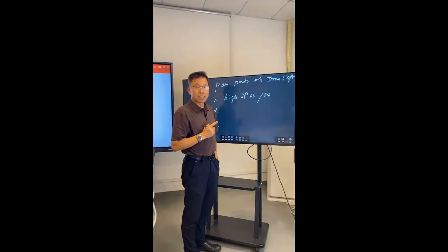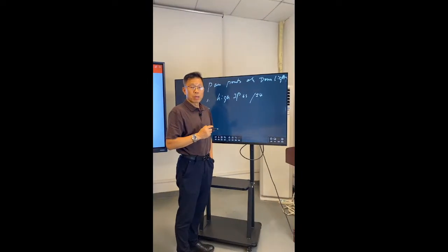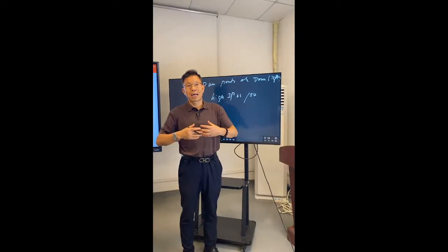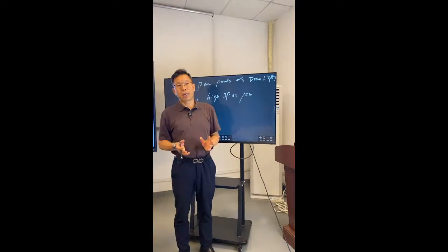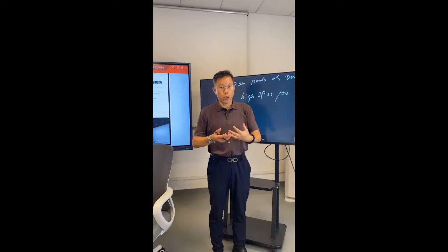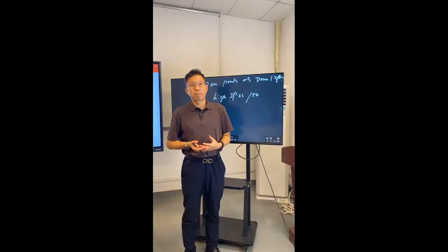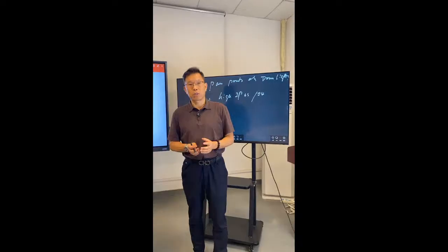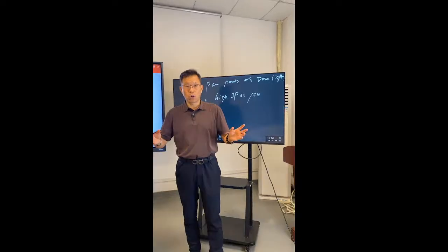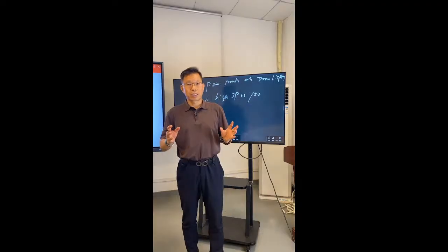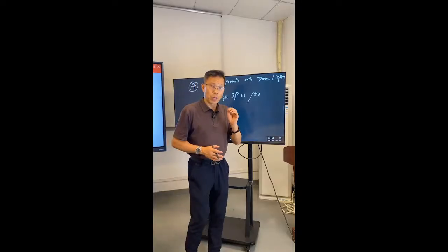And the second is that in the United States, people normally need housing to make the fixture IC rated. The trend is that people don't want to have the housing or the mounting plate because of the high cost of material and labor. So people need the downlight to be self-IC rated.